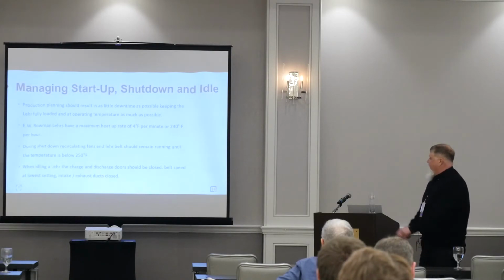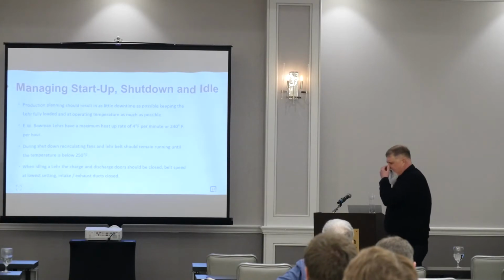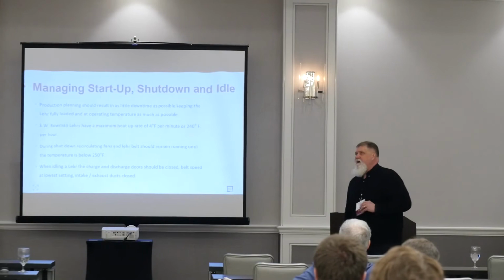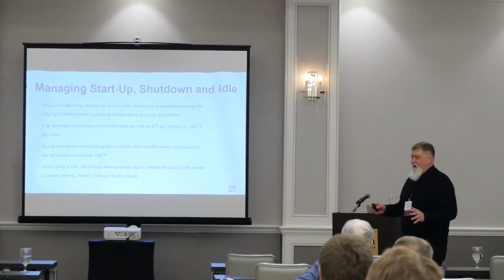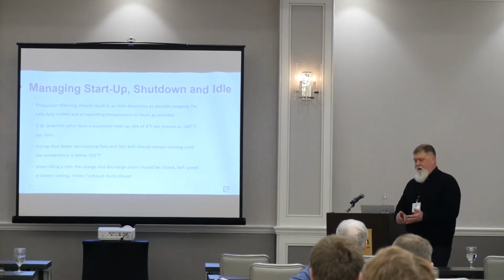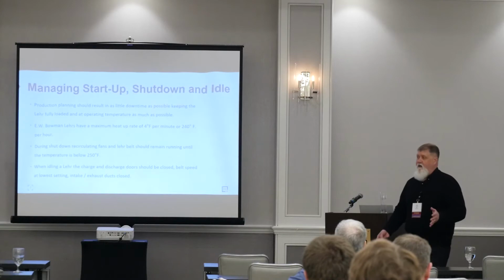Okay, so managing startups and shutdowns. I know I was talking to a few folks in here yesterday, and just so you all know, any high temperature decorating lehr, be it a Bowman or a Panicam or an Antonini or whoever's lehr it is, they are really built to run 24/7 and never shut off.